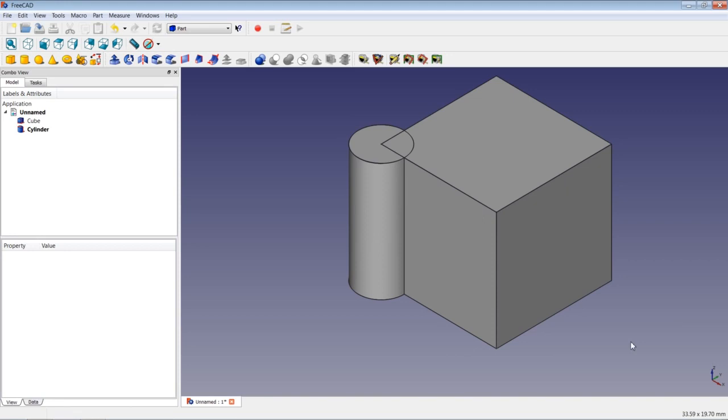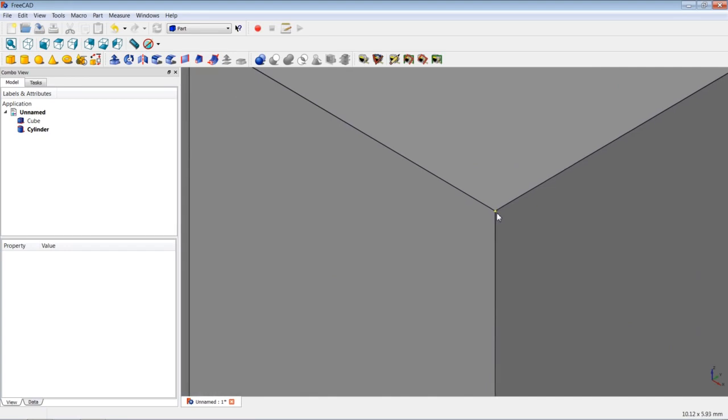Now as for the navigation style in 3D space, I am using here on my Windows system a normal Logitech mouse. It has two buttons and a scroll wheel in the middle. So if I point with the cursor somewhere in 3D space, and if I now turn the scroll wheel towards the screen, I will zoom in.